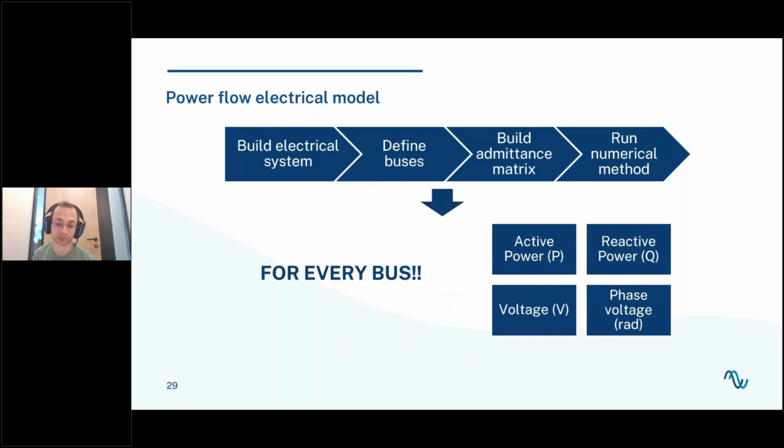The most important one is probably the point of interconnection because it's the one that the TSO is asking for, but it's also important to know the values at the inverters, for example, to ensure that they are not working outside the voltage range. So we need to ensure that all the equipment is working accordingly at voltage ranges that they can work at.